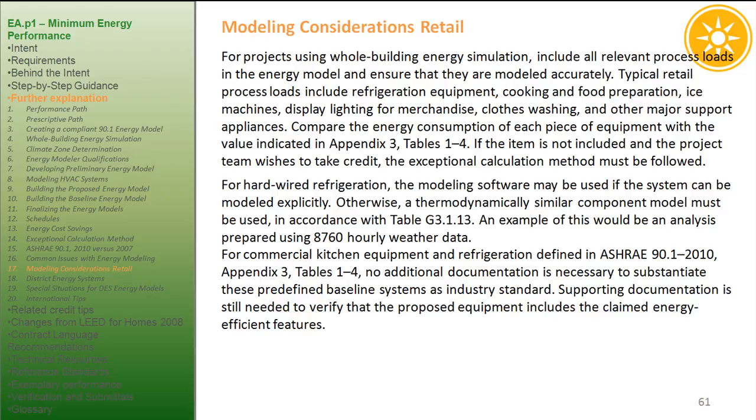For hardwired refrigeration, the modeling software may be used if the system can be modeled explicitly. Otherwise, a thermodynamically similar component model must be used, in accordance with Table G3.1.13. An example of this would be an analysis prepared using 8,760 hourly weather data.